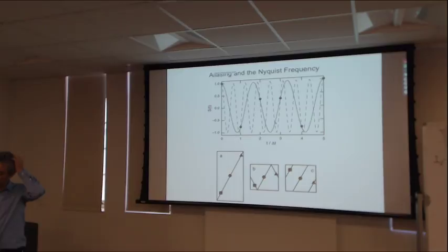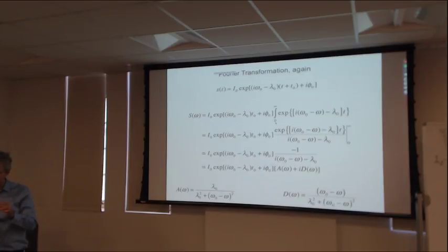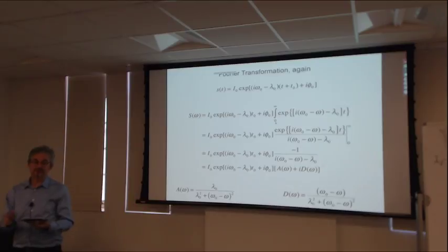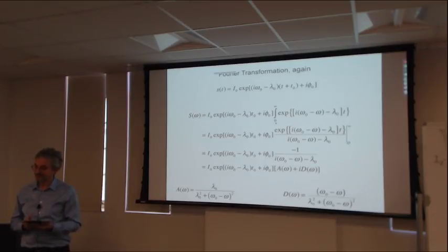But those modes of data collection aren't used so often these days. That's probably enough. All I want to say about sampling right now is that we have this requirement that the increment be small enough to cover the spectral width we're interested in, and then the total time be long enough for the resolution to resolve the signals.